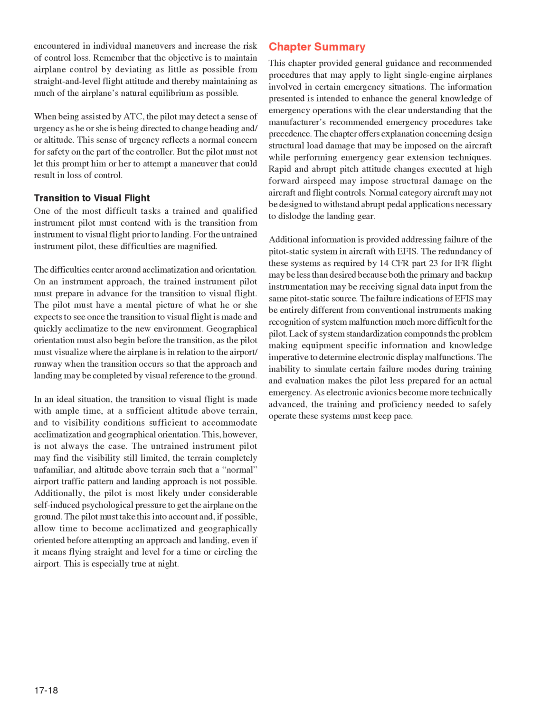The pilot must take this into account and, if possible, allow time to become acclimatized and geographically oriented before attempting an approach and landing, even if it means flying straight and level for a time or circling the airport. This is especially true at night.